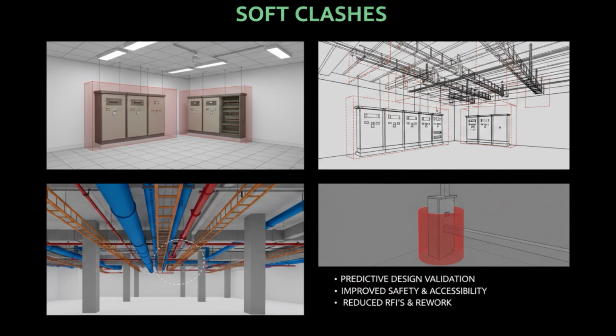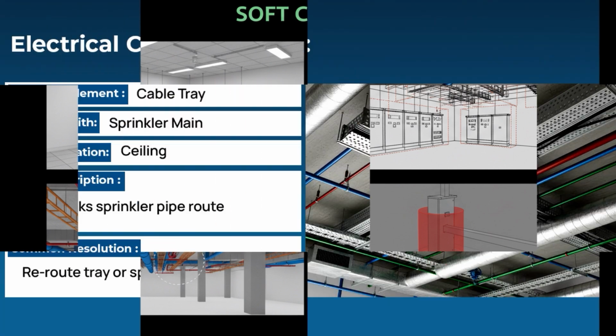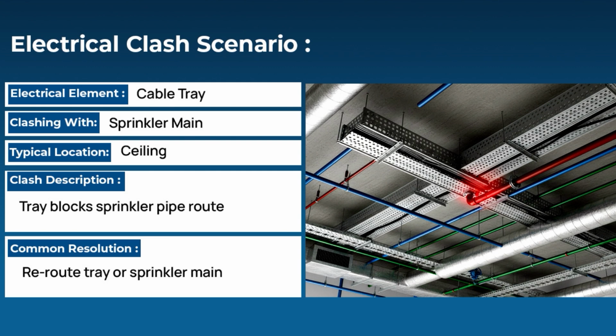This happens due to insufficient maintenance clearance of the switchgear. This can be resolved by increasing the size of the room or adjusting the size of the switchgear by modifying switchgear sizes. Transformers with the wall equipment. This can happen in substations. Here, the transformer needs clearance, to access the transformer or for the cooling purpose of the transformer, so there can be clashes with these clearances. These can be adjusted using the repositioning of the transformers.